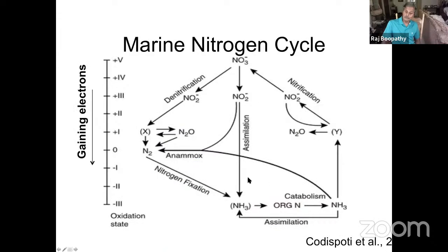So we just looked at using the nitrogen cycle. We know we started with high ammonia. So we wanted to use a nitrification process, convert this ammonia to nitrate, allow the bacteria, the Nitrosomonas and the Nitrobacter, to do this oxidation, and then do the denitrification step, convert nitrate back to nitrogen gas. So you remove this nitrogen, this partial cycle of nitrification and denitrification in our design.